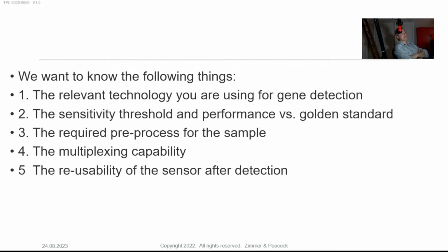If you've got a high genetic load, then the assay time is shorter. When it's a small genetic load, the assay time is longer. But I think fluorescence and electrochemistry stack up pretty well. The one thing about fluorescence is if you're going to make a point of care device out of it, you have a mechanical burden because you have to shield that entire assay from the ambient light. So I do prefer electrochemistry. If you have a biology background, you're used to fluorescence, you'll make a fluorescence point of care device. If you come from an electrochemistry background and the world of low cost glucose strips, which we do, then we would obviously prefer electrochemistry.